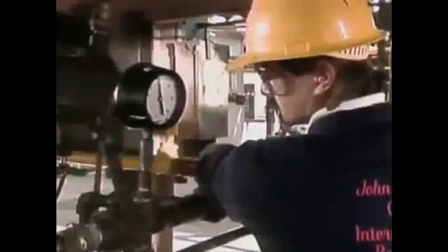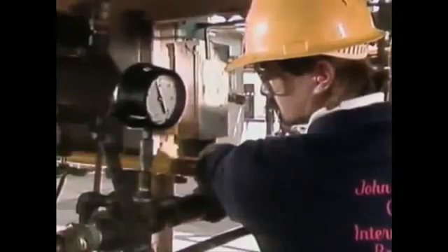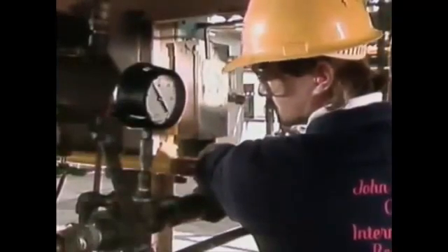An abnormally high fuel pressure could lift the flame off the burner. Therefore, decreasing the fuel pressure corrects the problem and brings the flame back toward the burner. If the fuel pressure is too low, the flame could burn inside the burner tips, producing a whistling sound. Most of the flame patterns and burner adjustments we've seen are for gas burners.